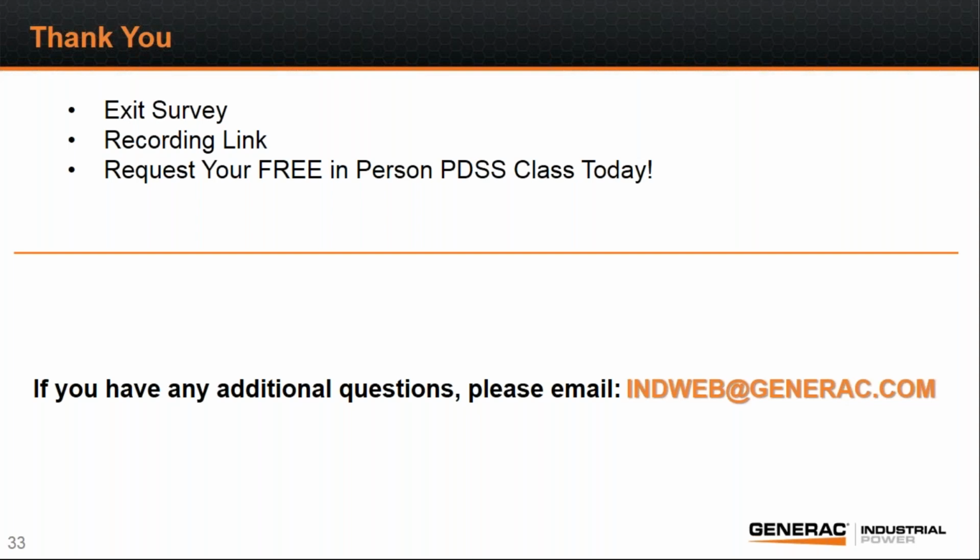What can you tell us about generator sizing where ISO 8528 G3 compliance is a requirement? The ISO requirements, you need to be a little careful because unless you're really up on your G1, 2, and 3 compliance within that ISO standard, it can be a little challenging. That standard has some tables in there based on, if I remember right, BMEP of the engine that you can make some pretty significant adjustments.